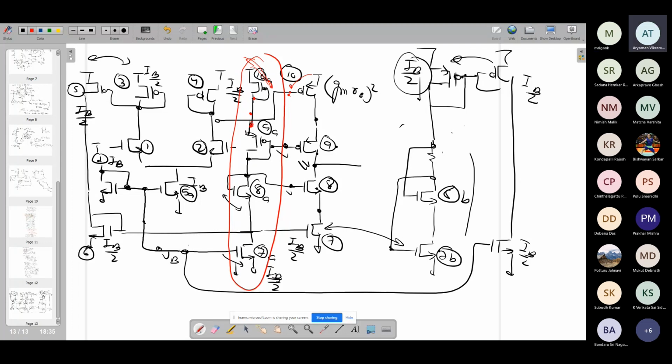Okay, yes. And so the right one, this one is our cascode, right? So we had discussed this reduced swing cascode mirror. Do you remember? Reduced swing cascode current mirror. Yes, the same thing. So what I have done is, this is like a current source. This is just providing a particular current to this branch, right?